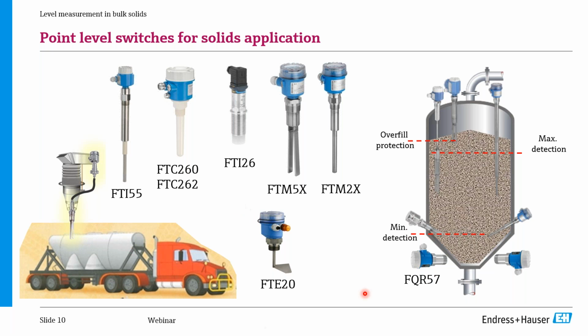But since you have moving parts, they are more prone to maintenance and damage depending on the process conditions as well. And from an installation perspective, they can all be installed from the side, as you can see here, for minimum or overfill protection, and also on the top of the tank. It depends on the objective behind the instrumentation.